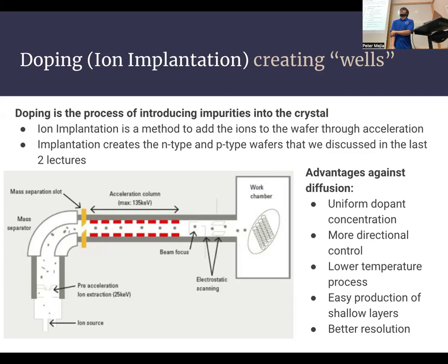Does anyone have any questions on ion implantation? We have a machine that does it. Well, we're not going to be doing this in the lab, but if you want to do it in a later year, when you have a little more experience, then MOSFETs, maybe? Would you need this for MOSFETs? You'd need something like it to dope the gate, or the source and drains.